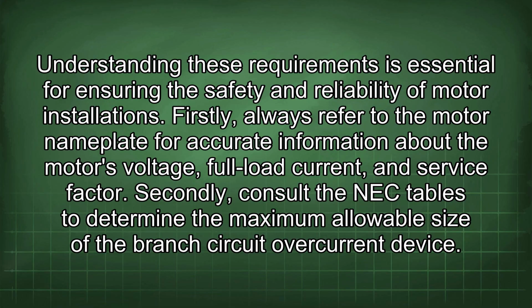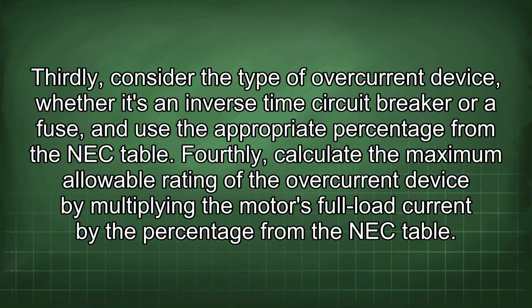Secondly, consult the NEC tables to determine the maximum allowable size of the branch circuit overcurrent device. Thirdly, consider the type of overcurrent device, whether it's an inverse time circuit breaker or a fuse, and use the appropriate percentage from the NEC table.